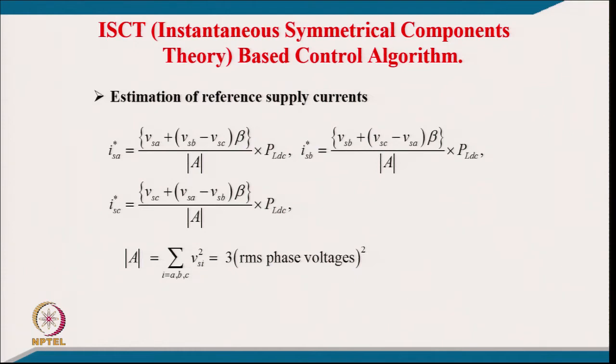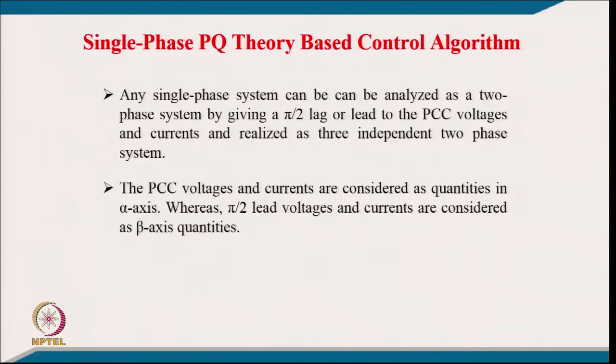So, that explains this instantaneous symmetrical component theory, which was devised in 1957 and used extensively in power networks, either power systems or other applications, even for electrical machine analysis. It is used in the same way as the couple of theories we already talked about, the instantaneous reactive power theory as well as the DQ theory. So, this is another theory which is used for control of the DSTATCOM.